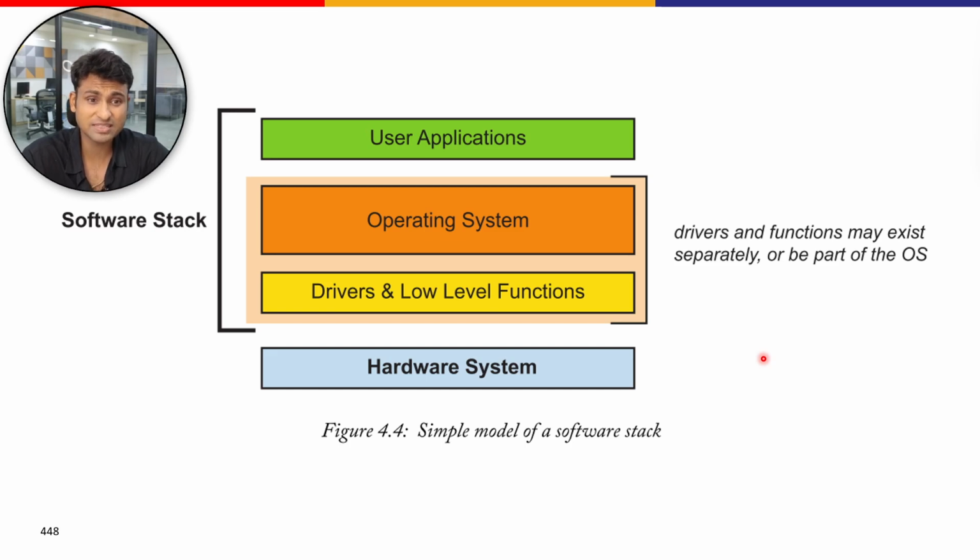Most notably in the Zynq MPSoC, given that it has several processing cores split as APU and RPU, there could actually be several software stacks running. This is just one stack; there might be a separate stack running on a different processor or maybe a different core of the same processor. There may also be further software stacks in the system associated with the platform management unit, the video codec unit, the DPU, the deep learning processing unit, as well as any soft MicroBlaze processor cores implemented in the PL. There are more permutations